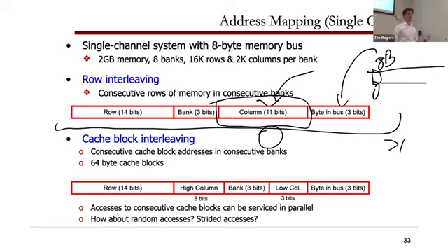So the very first address, this is 0. And then the next 3 bits are just associated with the data that's inside here. Then the next address here is 1. So as I scale up this number, from 0 to 1, that becomes the index for the column, right? So that means that in consecutive columns of a row, I am storing consecutive 8-byte segments of a cache line.